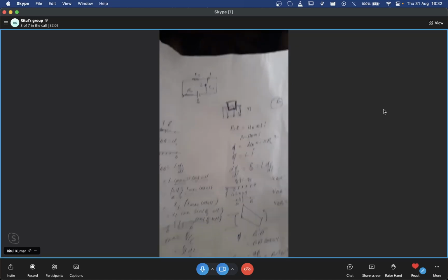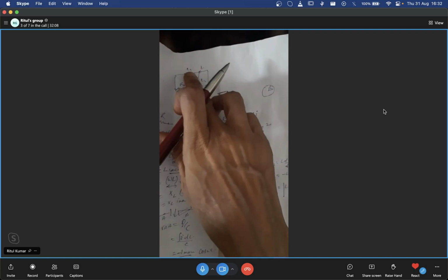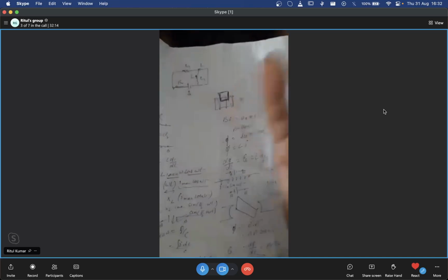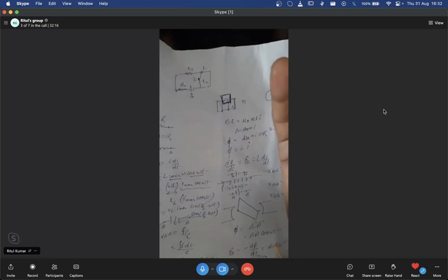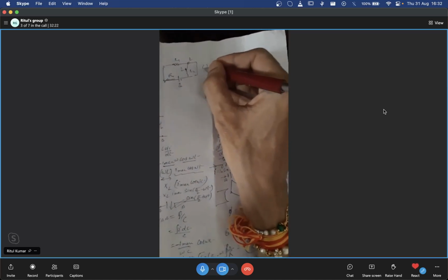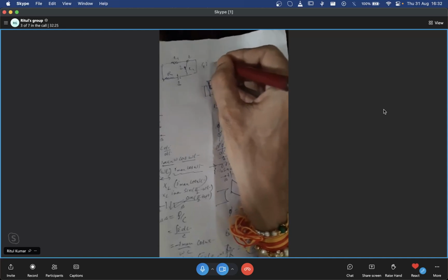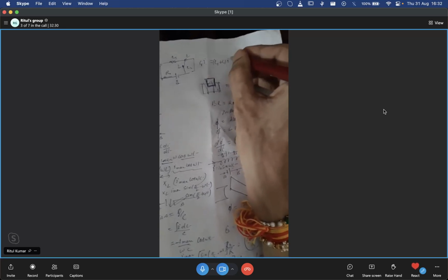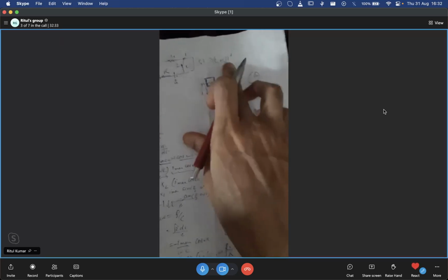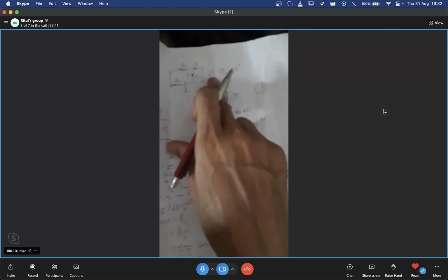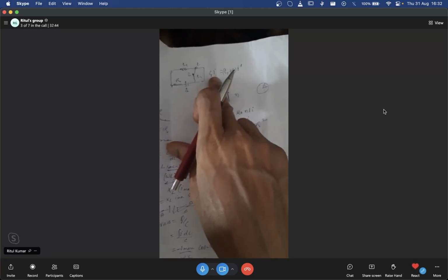So over here as well, when there was flux at any point in time when I switched it, what was the flux through it? Flux through it was Li. It will try to maintain it. So what will I write in this case? L1 I initial is equal to what? We'll learn about how they add. If they are in series, L1 plus L2, and then what current? I prime. So I get immediately a current at t equal to 0. Someone will ask, what is current? You will say at t equal to 0, current is L1 into I divided by L1 plus L2. It is not 0.